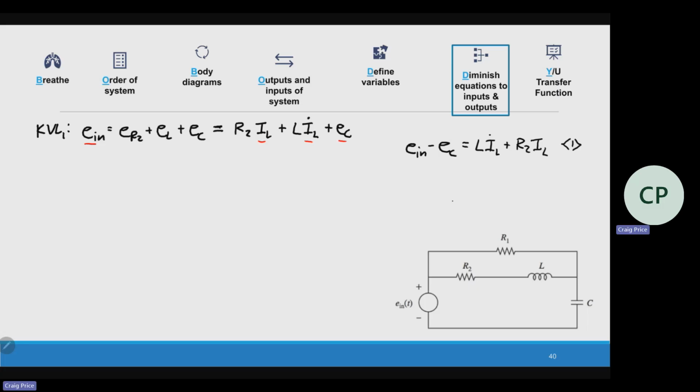I don't have any other derivatives. It is just my one output variable, IL. And so really the difference in these two voltages is going to dictate what that current is like going between on that leg. So this is a good way to format it. It's just trying to keep all the output variables together, highest order first. Then we've got this. I can't make a transfer function out of this because I have a difference there. So it's like two inputs giving me the current. Questions?